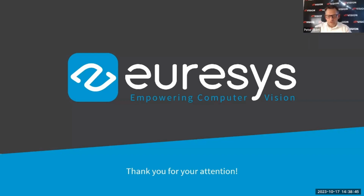Next question. What is the maximum multiplication and division factor of the rate converter? So the maximum division is by 1000, and the maximum multiplication is by 1000. There is a limit, of course. The multiplication cannot be higher than 5 megahertz. But to be honest, I don't know any line scan camera that supports a line rate of 5 megahertz. So we have, I think, a comfortable margin regarding this.